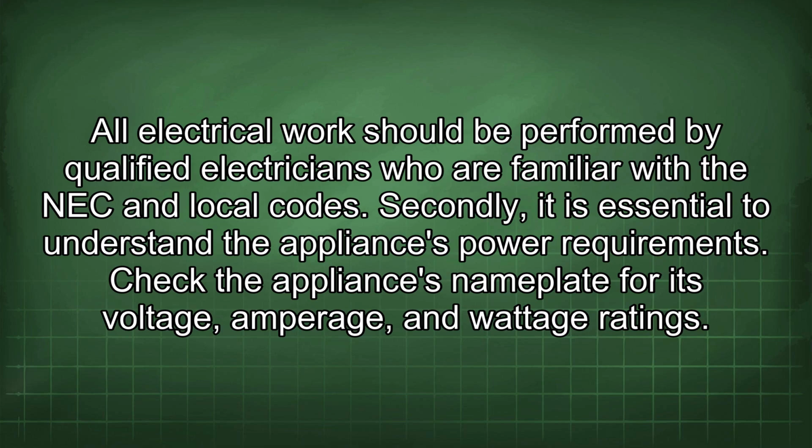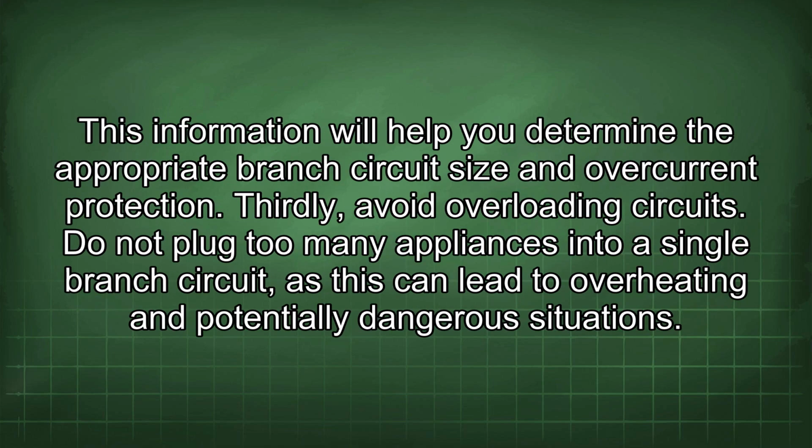Secondly, it is essential to understand the appliance's power requirements. Check the appliance's nameplate for its voltage, amperage, and wattage ratings. This information will help you determine the appropriate branch circuit size and overcurrent protection.